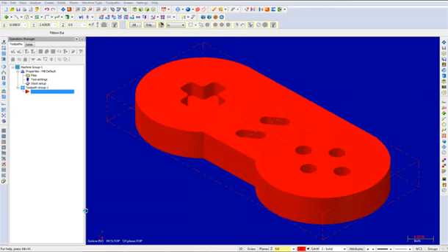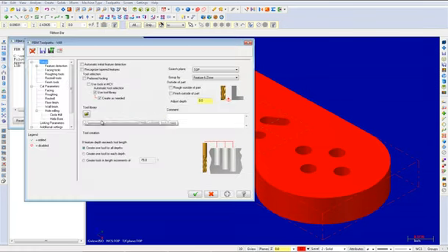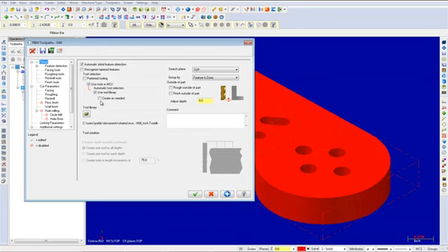Select Toolpaths, FBM Mill. Enable automatic initial feature detection and use tools in MCX. Also, disable the following option, Create as Needed. The rest of your parameters should appear as shown. I will now take a brief moment to explain a few of these features.